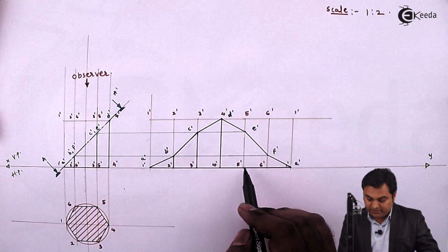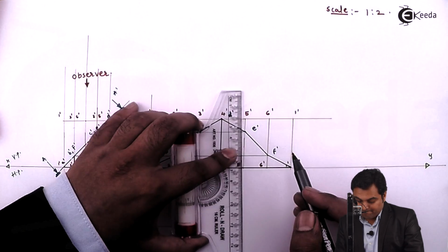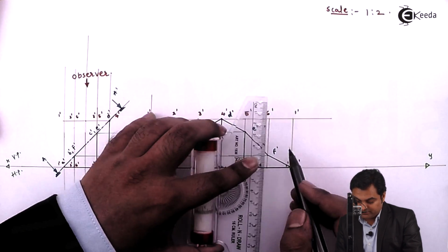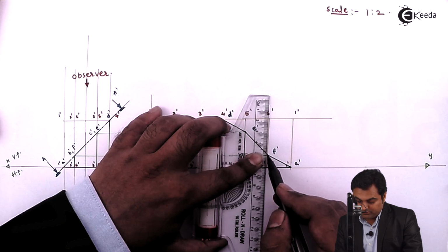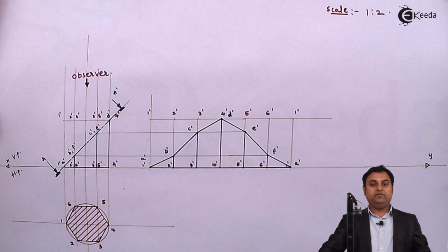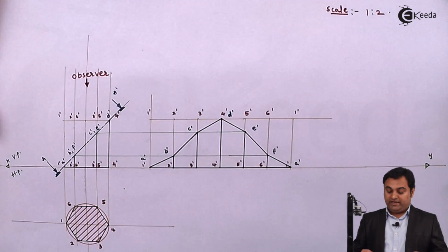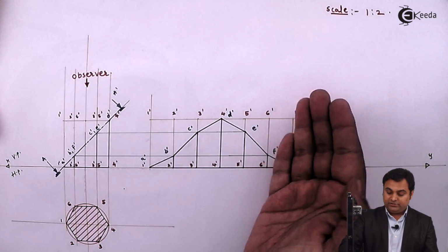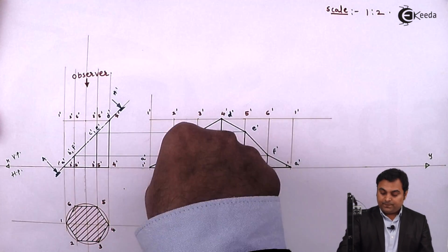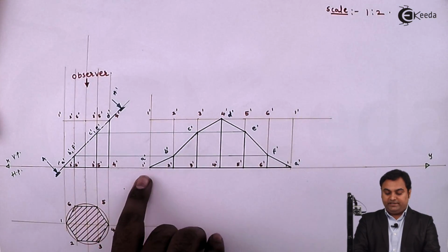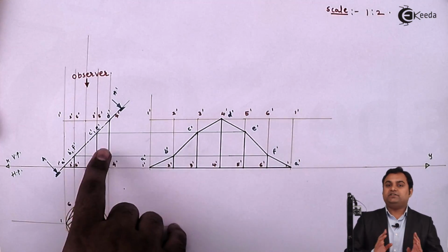then 5 dash with E dash, then 6 dash with F dash, and the corners are being cut at A dash. So in this way, the development of the hexagonal prism will look like this. For example, if I am going to fold it about its dark edges, and then turning it and joining A dash with A dash, I am going to get this hexagonal prism.